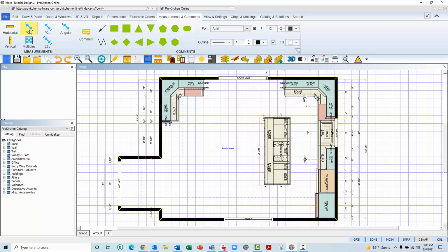to grab the tool. Bring the mouse into the plan view and left-click on the light that will remain where it is to start the dimension. Then drag the mouse to the light we intend to move and left-click to secure the dimension line. Now that the dimension line is set, we can adjust it.